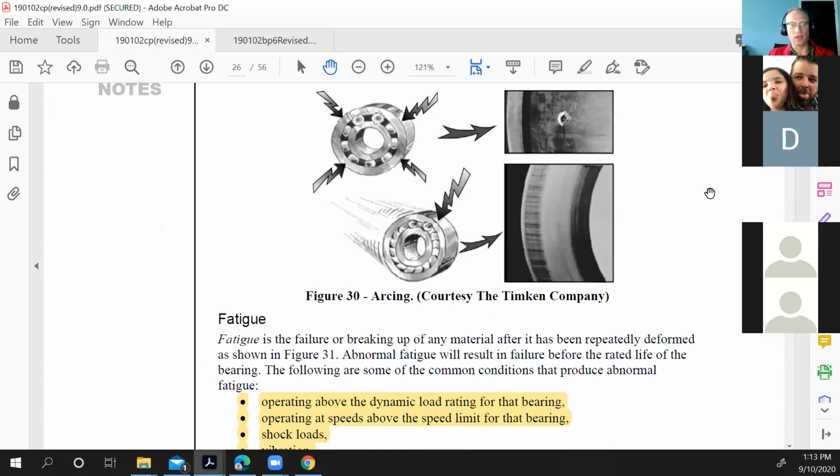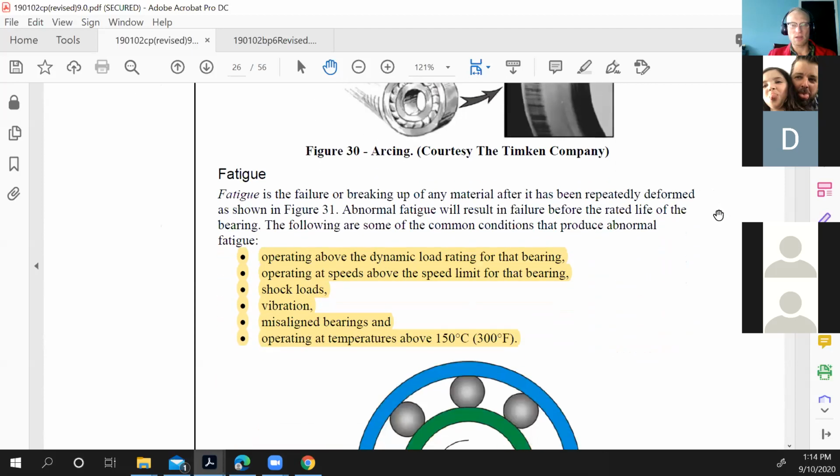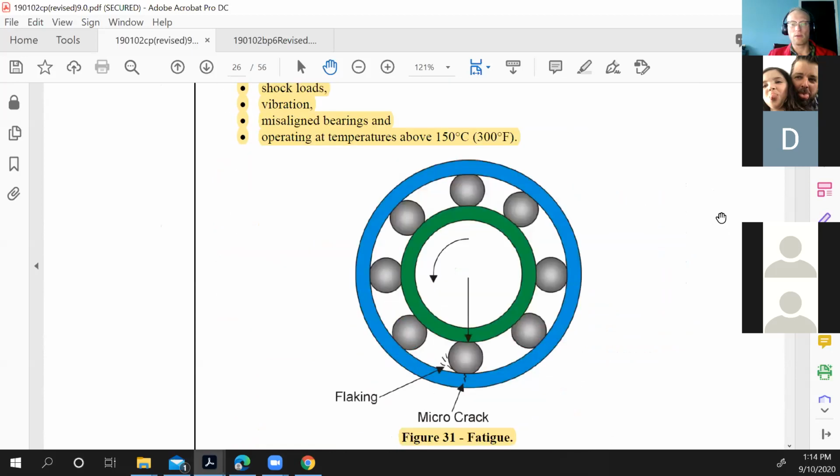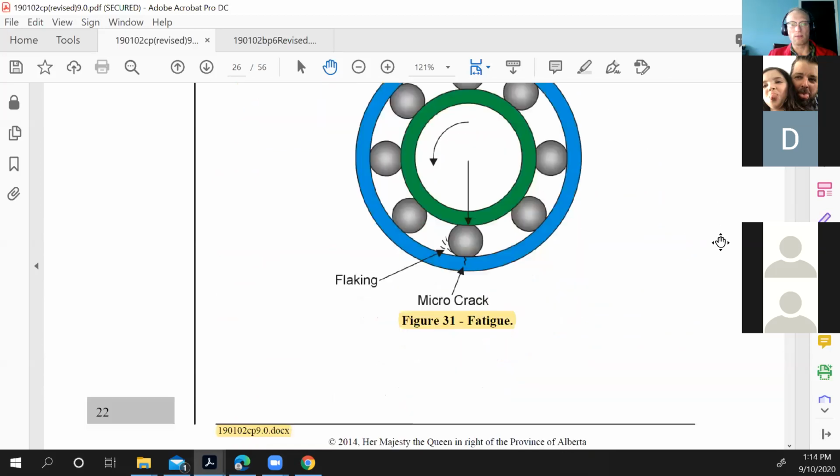That leads to totally other problems to worry about. But out here, it can get humid sometimes, especially on a cold day. You run an engine outside in the middle of winter, it gets really hot. When you turn it off, it draws in a lot of that humid, cool air, and everything condenses on the inside. Or in hubs too, you run hubs a little bit too warm and they draw in a lot of moisture, and then you end up with milky looking hub oil.